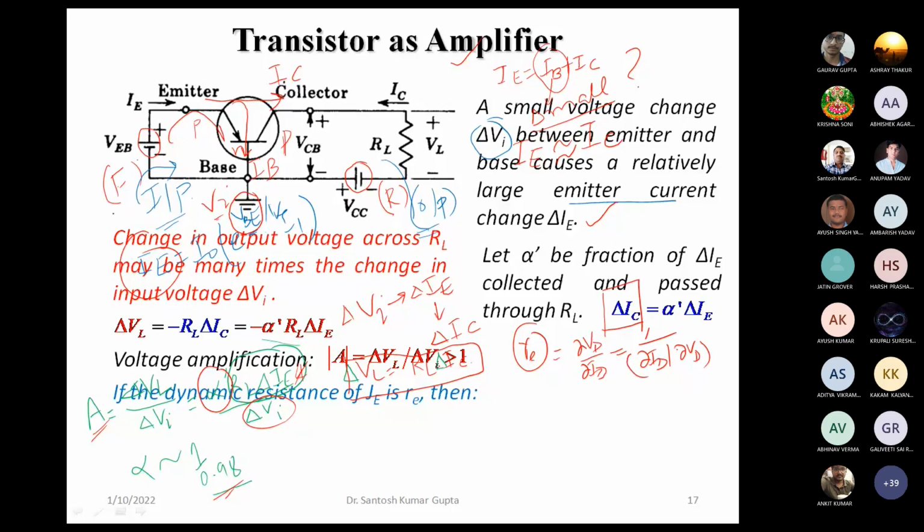Here for Vd we are just relating this with the diode parameters. So the diode current ID we have seen to be equal to I naught into exponential Vd upon Vt minus 1. So from here we can see that now in place of this ID we are having IE, and in place of Vd we are having Vi here.